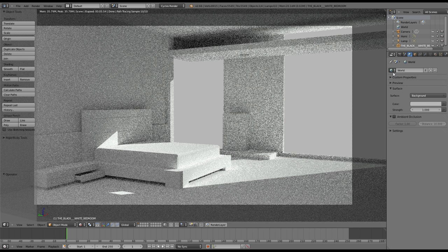You can see with what we're rendering at the moment, it's very pixelated. I probably should have pointed this out a little bit earlier, and I'll try to do that in my tutorial. You can see that it's extremely pixelated. Now the way an unbiased render engine works is that it becomes less and less pixelated over time. So the longer it renders, the less pixelated it becomes. This allows us to manipulate things in the scene and not have to go back, do it all, press a button, wait until it's rendered 6 hours, and then find there's something wrong, and then have to do it all over again. With this GPU method, we can change it all on the fly, and it's a lot more interactive, and it becomes a lot better workflow.